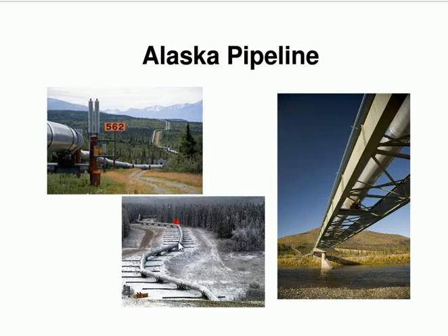That bit down here is quite interesting. What you see is a lot of wooden bars, and the pipeline is actually loosely laid onto this surface, and the reason is it's a fault line. So you've got tons of earthquakes there. As soon as you put any rigidity into the pipeline, there's a danger that it could crack. And so as far as the fault is concerned, they've got a very flexible type of system. So if there is an earthquake, it'll just shake a little bit, and then it'll sort itself out. So that's the theory behind it.